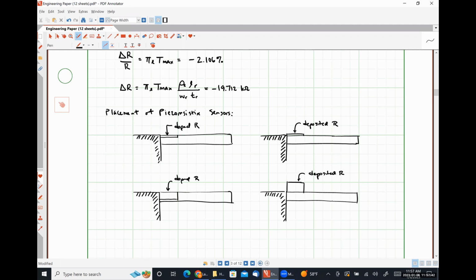And that's also an interesting thing. So with an extension rod, the stress is uniform across the entire cross section, right? So the location of our sensor doesn't particularly matter. You can argue that it might be best to make it the entire thickness of the beam, and its location along the length of the beam is completely and utterly irrelevant. But under the cantilever examples that we're looking at, the width isn't going to do anything but actually potentially improve the noise performance of the system.